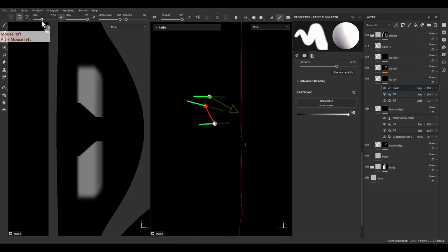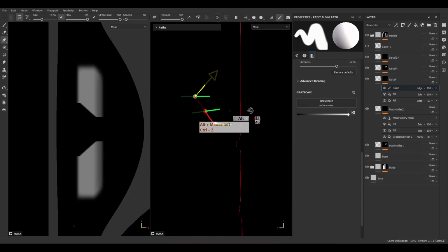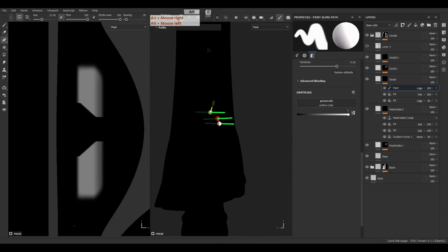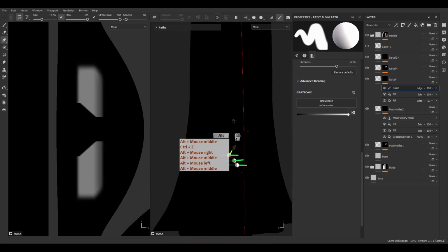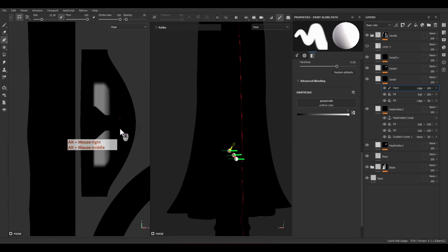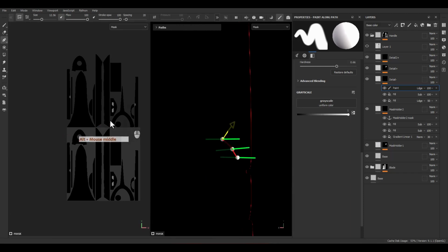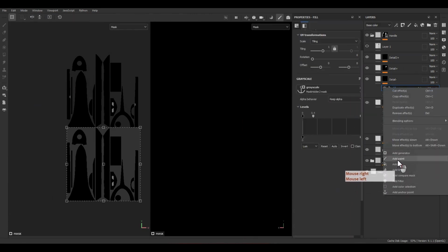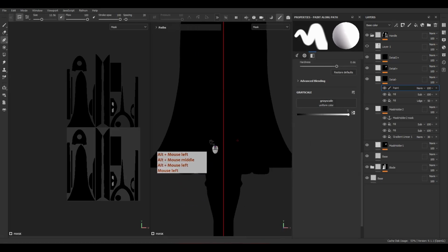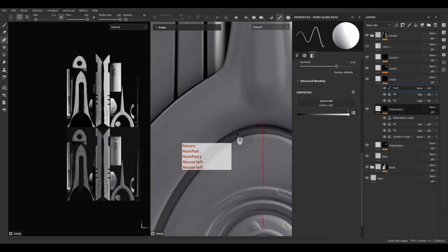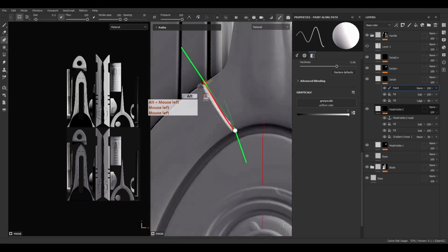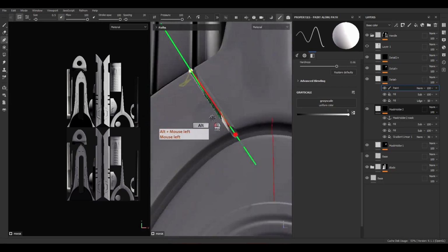Okay, what is wrong? So, I think I'm on the wrong side. This is the side outside of the UV tile. Whenever I paint here, nothing happens because this UV is not calculated inside the texturing process. So let's add another paint layer. Okay, and now I can add my detail from here to here. That's it. It's a straight line.